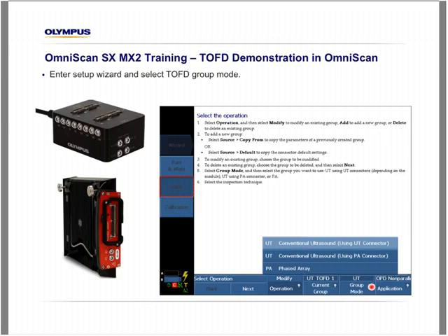We will see 3 modes of operation for the groups. These mainly are from where the group is generated and what type. For the TOFD, the normal and most common is use of the UT connectors. Use of the UT connectors directly on the OmniScan module allows a higher voltage and an independent high definition UT board, independent of the phased array, to generate the TOFD group. And that would be the conventional ultrasound using the UT LEMO connectors on the instrument that you see here.